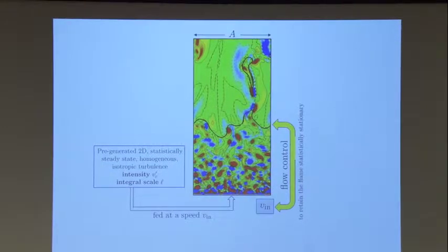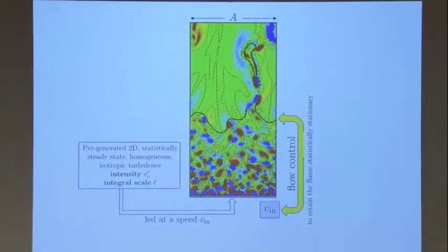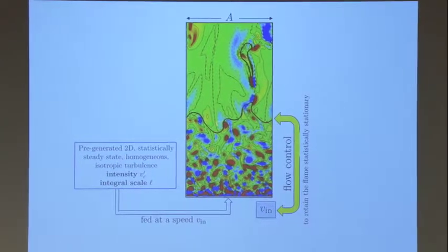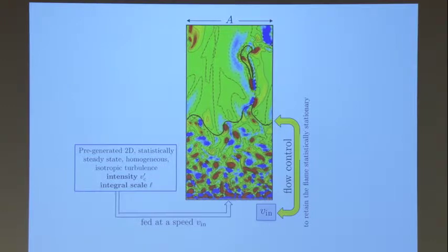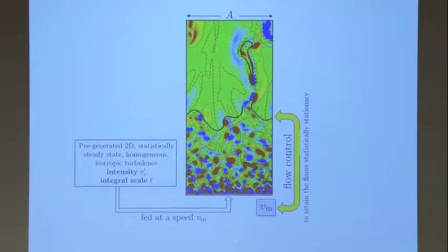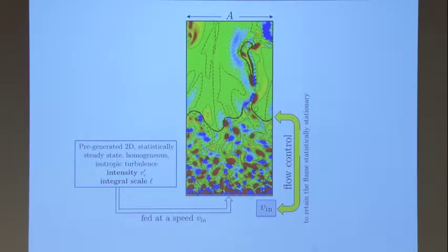What we want is to bring in here a turbulent flow with some mean velocity to get the flame stabilized at some position, and to ask what is the turbulent speed in this case, which can be computed either from the formula that I showed you before about the area, or from just the fact that the mean incoming flow is a turbulent speed. In fact, we did the calculation both ways, and both give the same answer, so there is no advantage of one over the other. It's just a check that you are still doing things correctly.